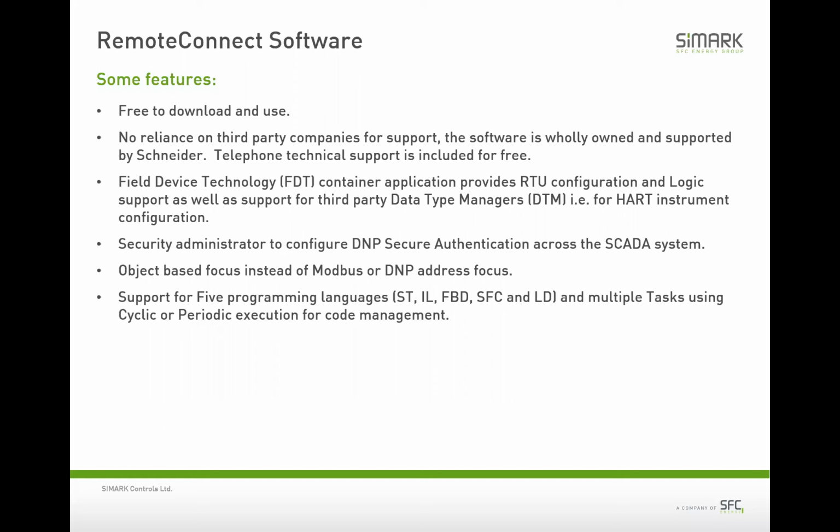With Remote Connect and the use of the Modicon programming software, we're back to offering structured text, instruction list, function block diagrams, sequential function chart, and ladder diagrams, as well as some additional multitasking options, giving you more flexibility about how code is executed within the controller in a cyclical or periodic fashion as well.